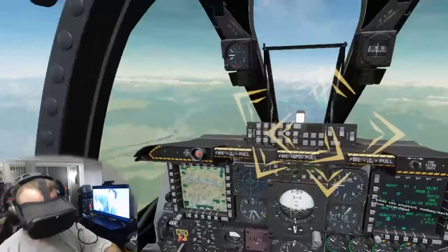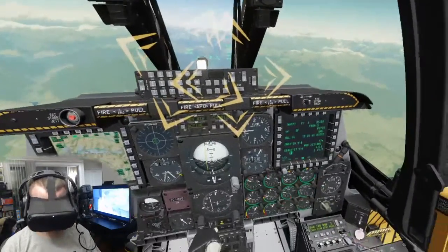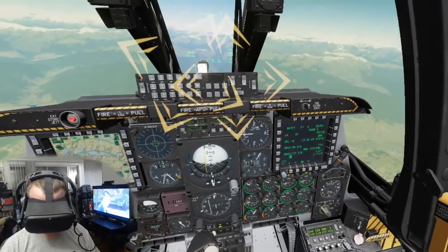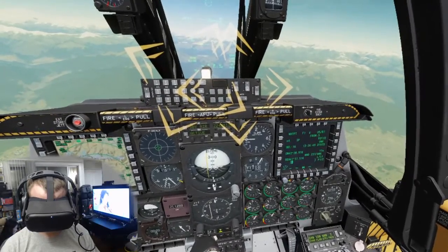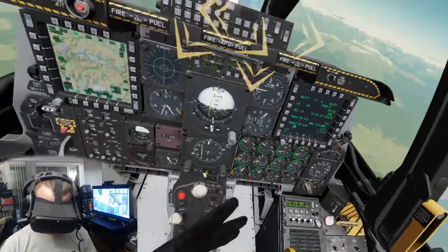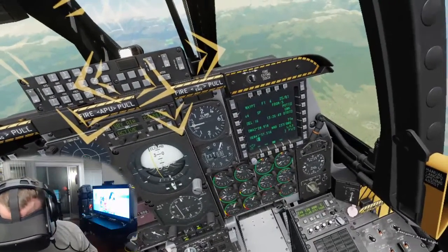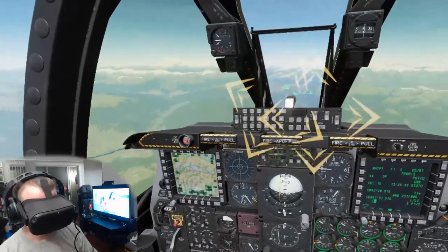You should now see detailed information about waypoint 4 Bolton on the CDU, including the waypoint elevation, desired time on target, and coordinates. Note, as indicated on the bottom right corner of the CDU page, this is page 1 of 2 of the display. To see the additional information on page 2, press the function key on the UFC followed by the data down rocker key.